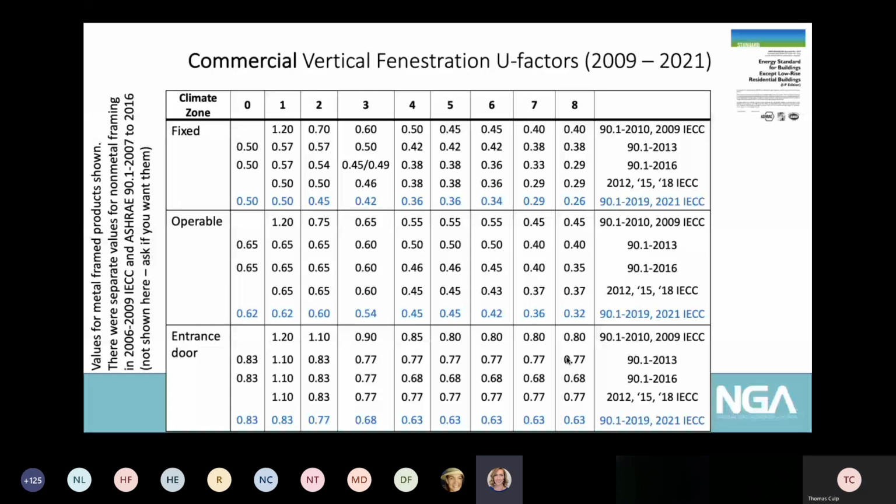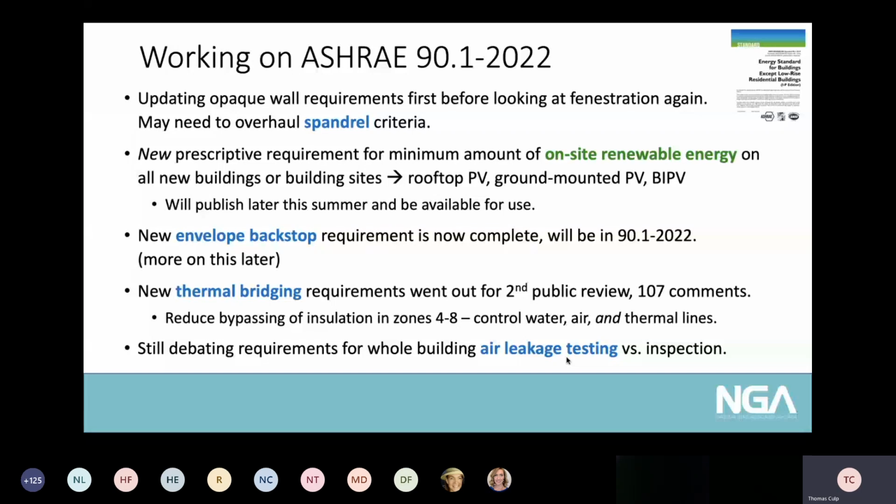Okay, one more question related to ASHRAE, and then we'll move on to a different subject. But to propose changes to the next ASHRAE 90.1 regarding spandrel, how early do those need to be presented? As soon as possible. Whoever that is, please contact me because I need as much help with that as possible. We've realized that it's an issue because they basically just set the wall requirements based on walls, and then they said as an afterthought, well, spandrel, let's just treat it like a steel stud wall because it's kind of metal framing. So they're treating it like a steel stud wall with foam insulation on the outside, and I can't even remember if it's 16 or 24-inch spacing, but clearly not like a spandrel. And they are starting to recognize it's not a good way of doing it.